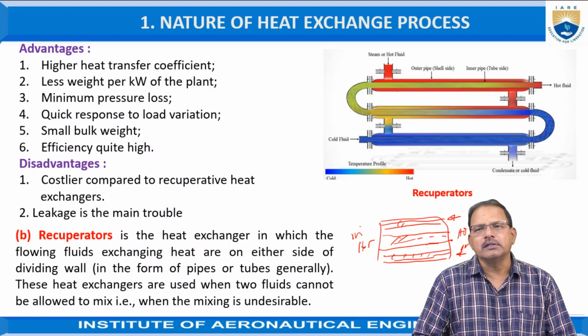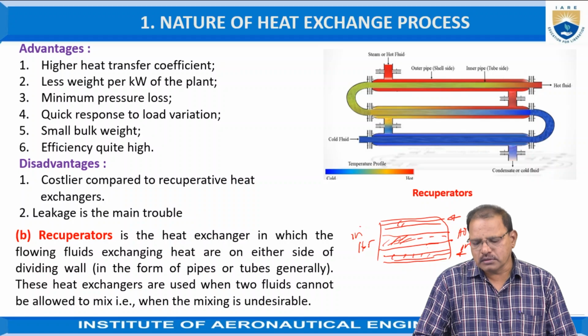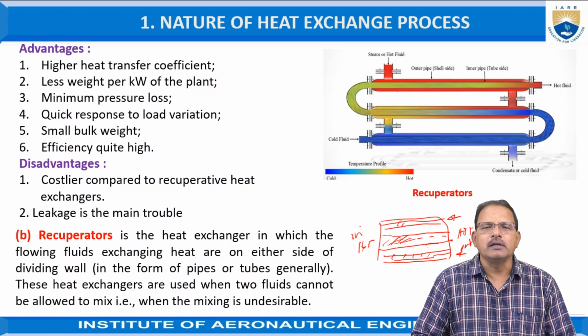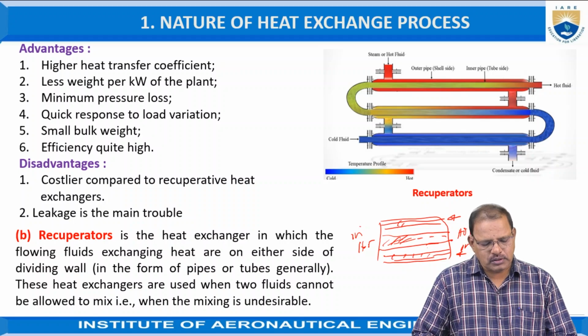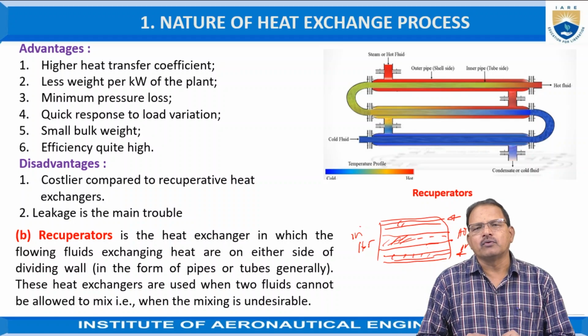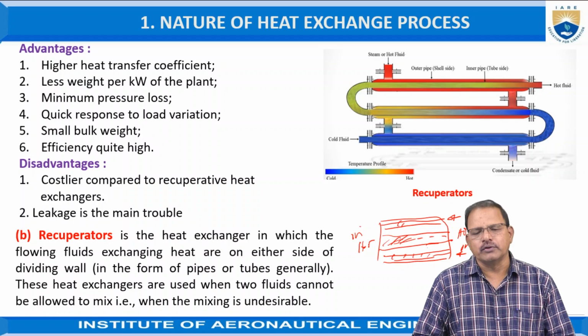In this case, the fluid flowing in the center tube is the hot fluid. The heat energy is transferred from the hot fluid to the cold fluids present in the remaining two tubes. These fluids may be different and are not desirable to mix with each other. So recuperators are generally used to heat cold fluids of different types using a single source of hot fluid.